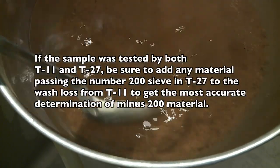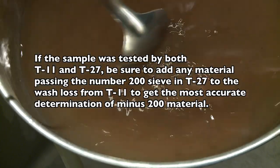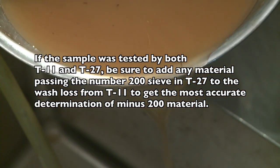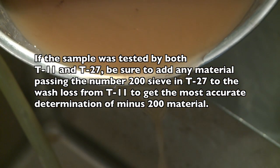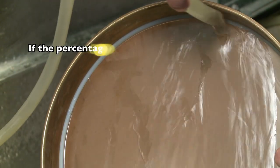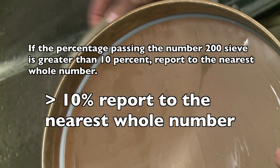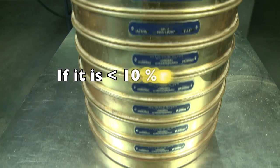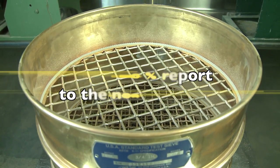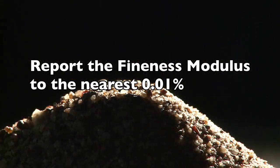If the sample was tested by both T11 and T27, be sure to add any material passing the number 200 sieve in T27 to the wash loss from T11 to get the most accurate determination of -200 material. If the percentage passing the number 200 sieve is greater than 10%, report to the nearest whole number. If it is less than 10%, report to the nearest 0.1%. Report the fineness modulus to the nearest 0.01%.